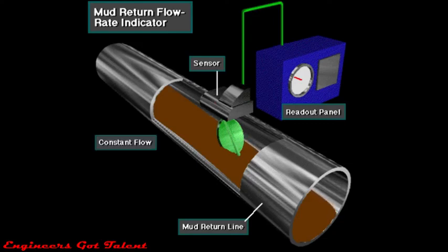The driller sets the readout so that as long as return flow is normal with constant pump speed and output, no alarm sounds or lights up.